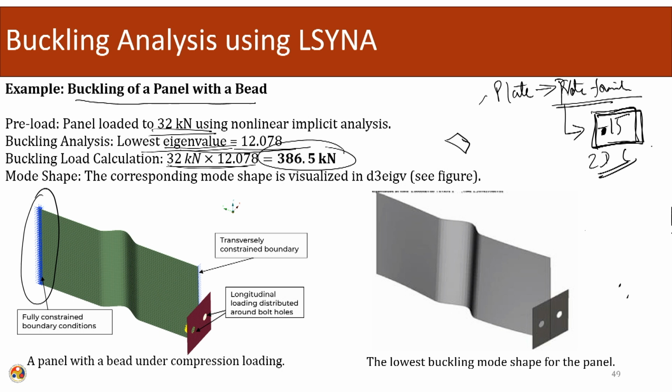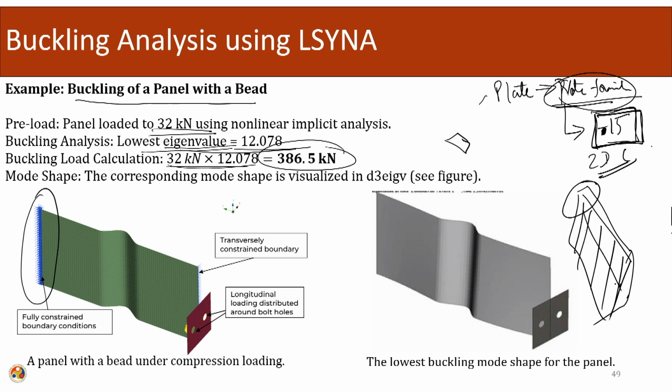So we specify the thickness of the system, and we have all the 3 dimensions: length, breadth and height. Then we have a plate formulation, solid formulation or any other type of plate formulation that we want to use, and we have a discretized plate. Once we have the discretized plate, we can choose all the nodes out here and give the constraints.